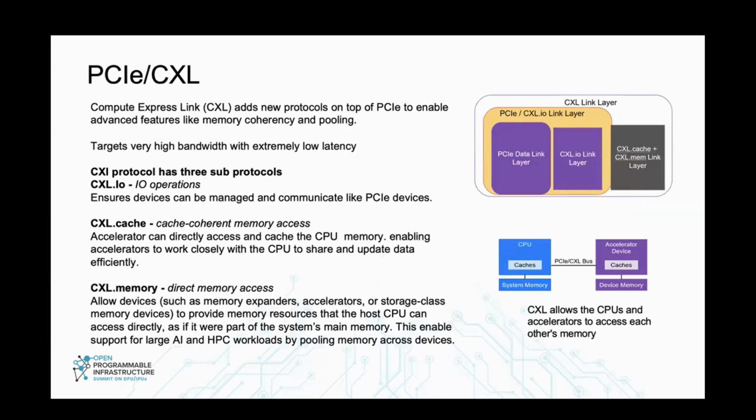Coming to CXL, it's Compute Express Link. It's a totally new protocol which gets added on top of PCIe. In the implementation background, CXL is an additional set of logic which gets added apart from the PCIe logic which sits in the controller. Generally, this logic's operating frequency is double the frequency of the data operation. So it's fairly critical when we have PCIe with the CXL protocol. Timing closure becomes very crucial in the design.